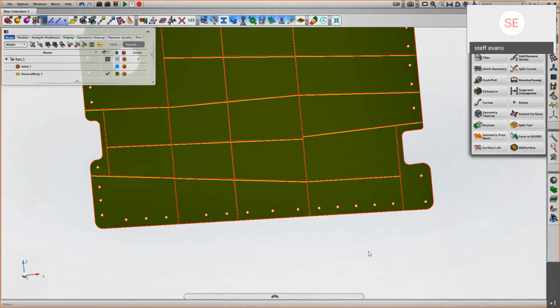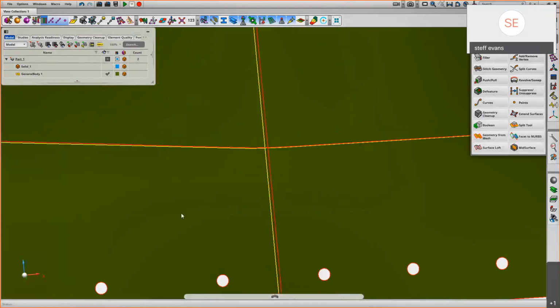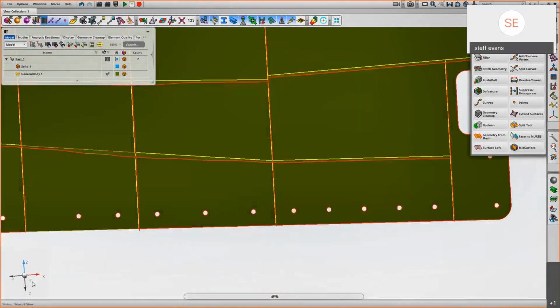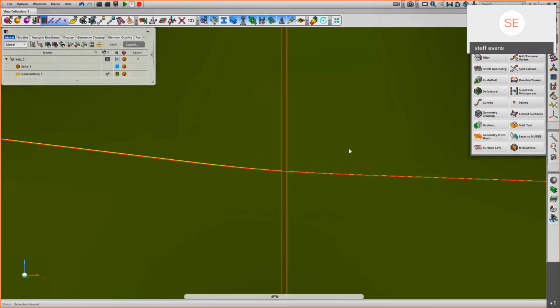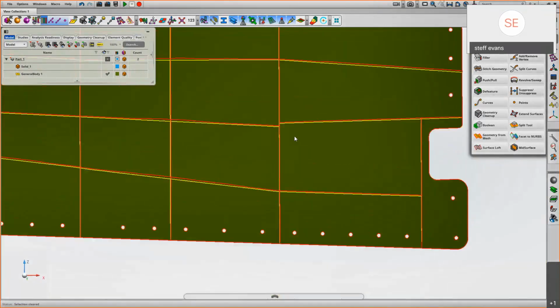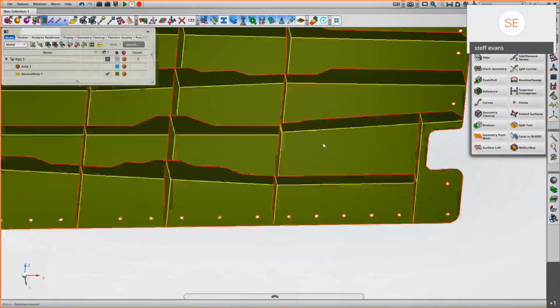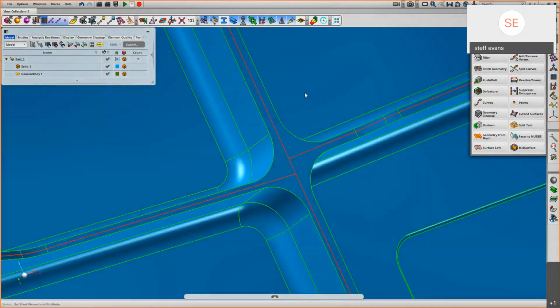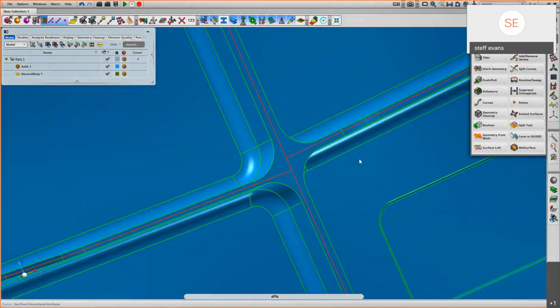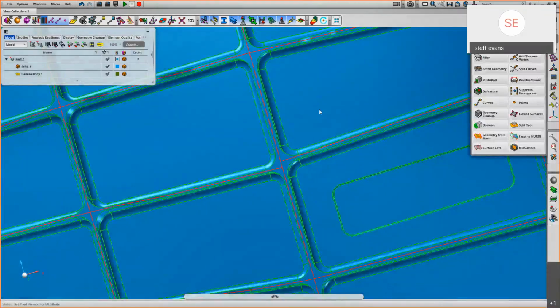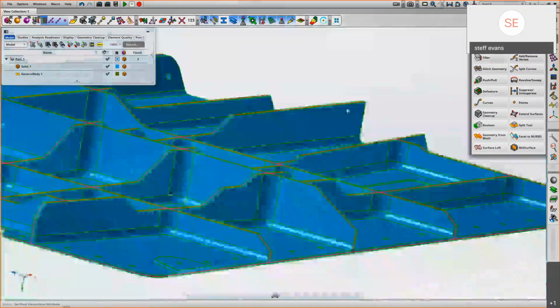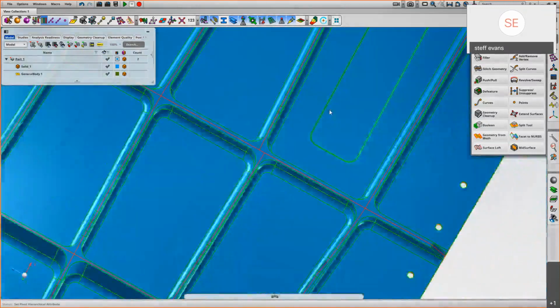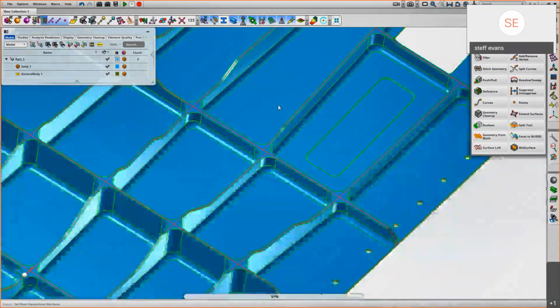If we look at the model in plan view, we can see a typical cruciform where 4 surfaces have come together at a right angle. Okay, but there's one area where we don't have that cruciform geometry, so we can manipulate this if necessary. Probably not the best practice to have these offset stiffeners in this type of model, but it looks like the underlying CAD has got that. We could go with the model as it currently is, or we could tidy things up. We're going to move the profile to give us a cruciform geometry